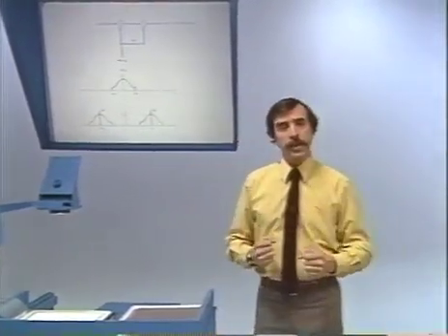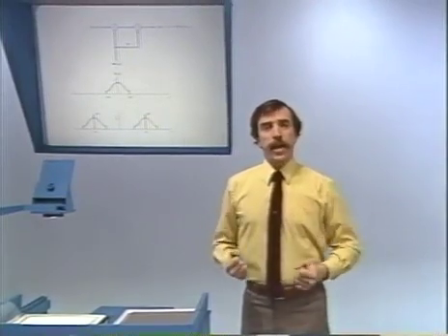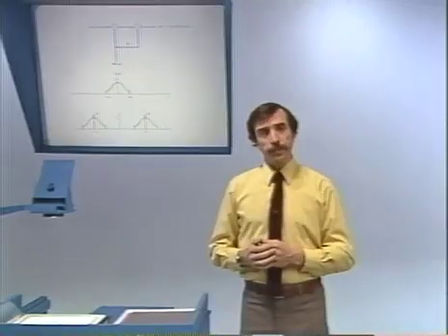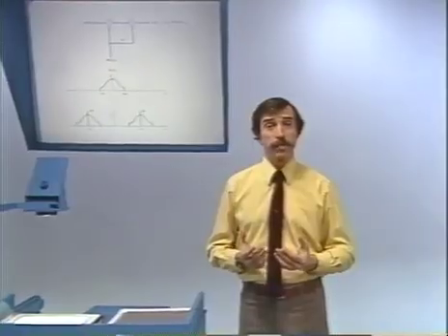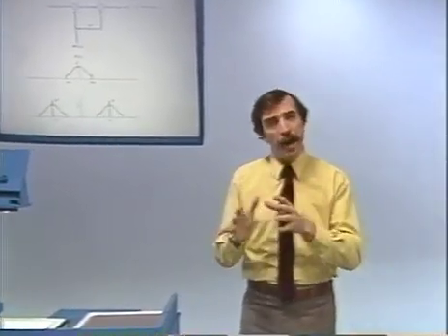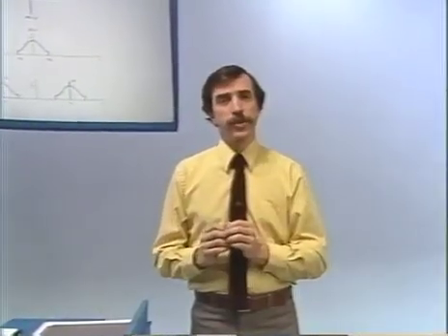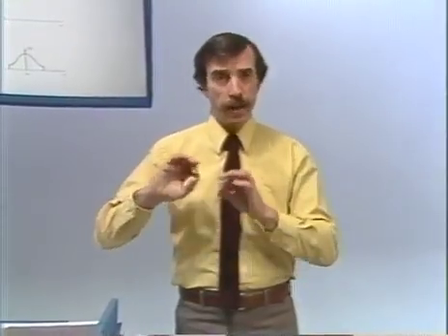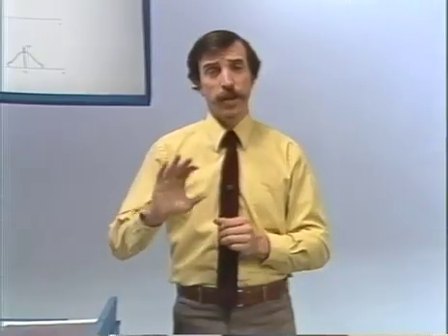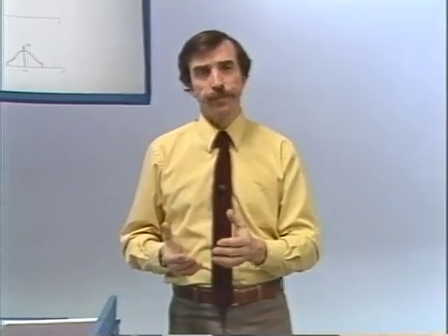Well, the obvious answer is that it's not an information carrying part of the signal. In some sense, it represents an inefficiency in transmission, because what you're transmitting is power, energy, that doesn't have any information associated with it. It's simply the injection of a carrier to make the demodulation easier for an asynchronous demodulator.